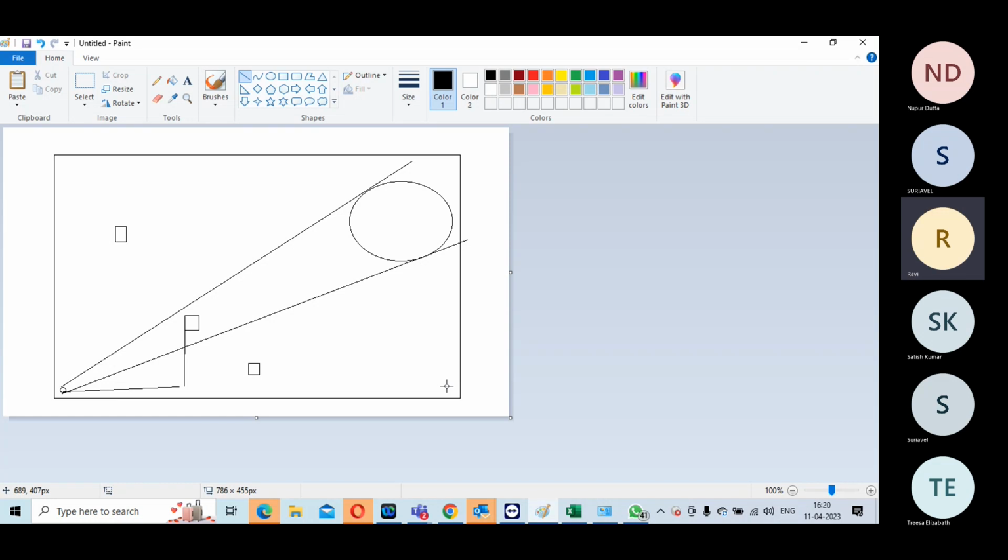Then like test logic, right? This is one functional clock, this is another functional clock. They are not related to each other. But in the scan mode, they can have interfaces. Then you should add lockup latches to disconnect these two so that even if there is skew, you don't get hold violation. Half cycle path you will benefit, you will get. You understand? So you work on things like that.